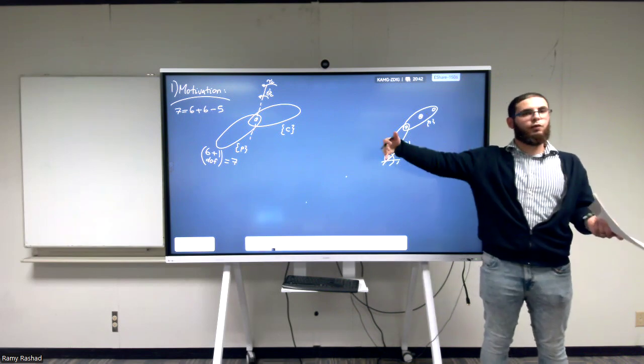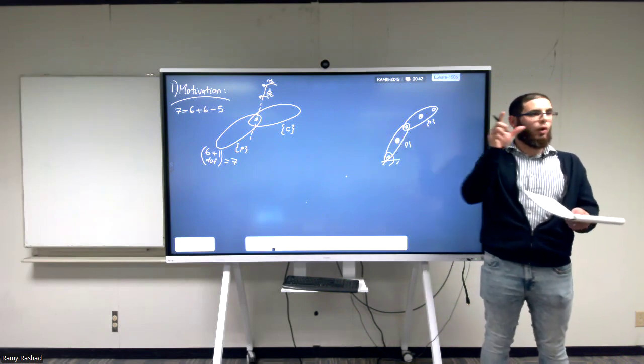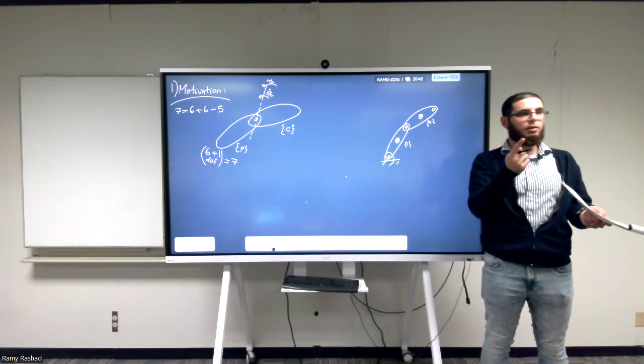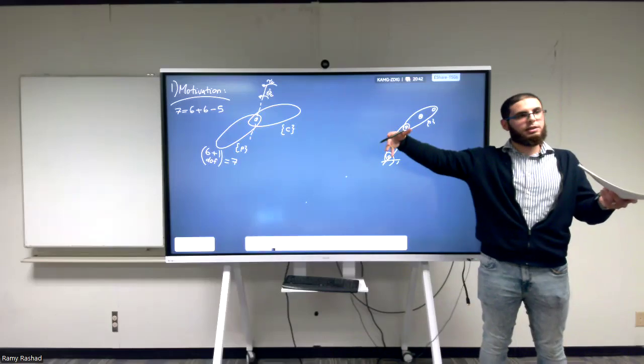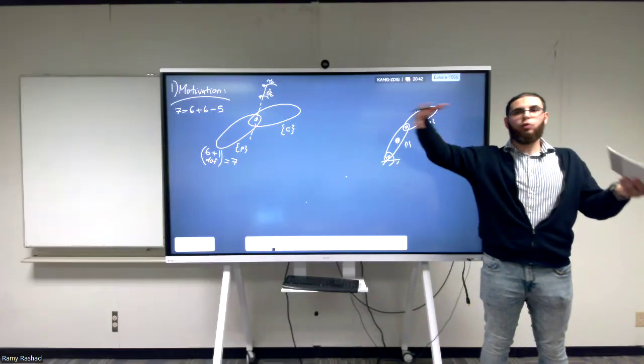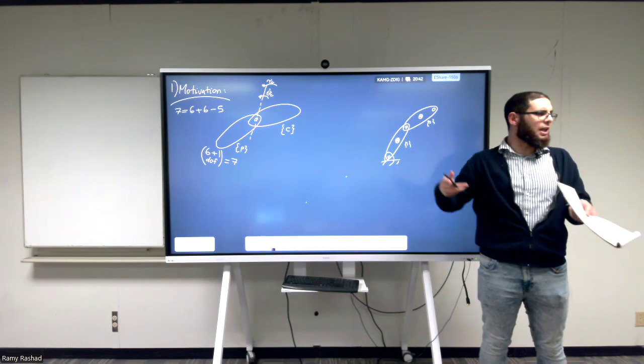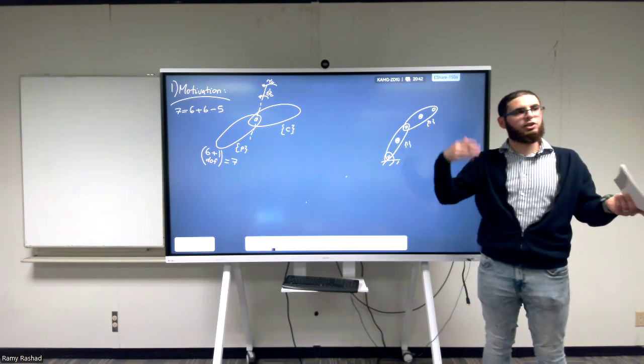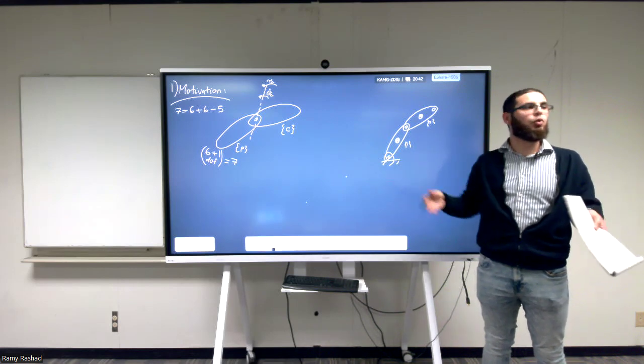Of course, it will be more involved because here we had only one body and we canceled the dynamics. So we reduced from 6 to 1 degree of freedom. Next time, we're going to have 2 rigid bodies and then reduce the 12 degrees of freedom into 2. So it will be just a little bit more involved. But after that, it will be just recursive. We're going to write it in a general way such that you can put it on the computer and it will do it for you.